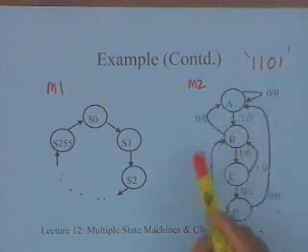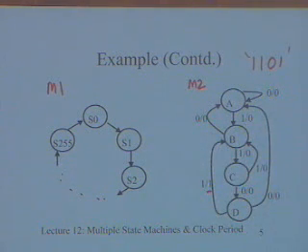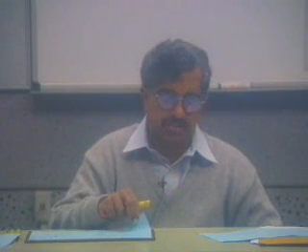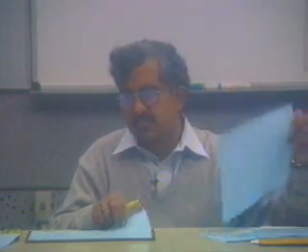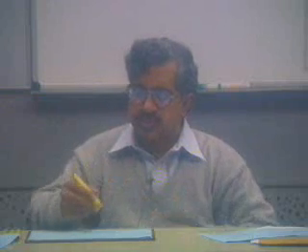Now, this is a state diagram for M2, and what I really need to do is design this, let us say, complex or multiple state machine. It is a combination of both M1 and M2, because what I now need to impose is that I do not permit my pattern to cross block boundaries, where the block definition is 256 bits. So the diagram is now going to look like this, a machine which has both M1 and M2.